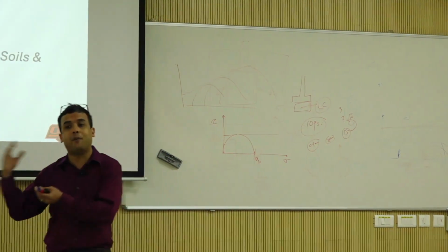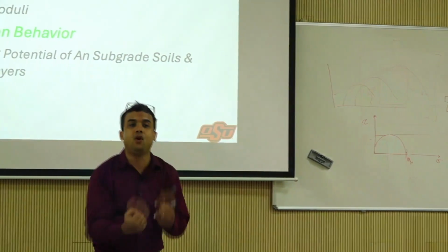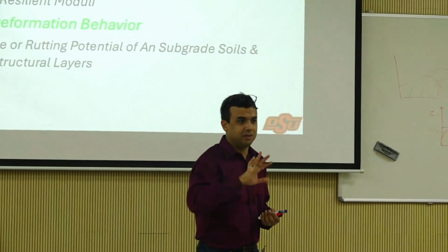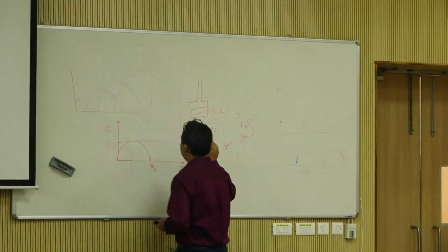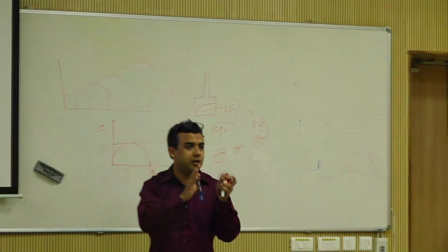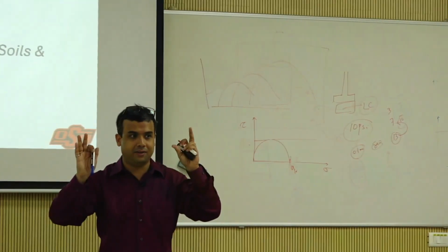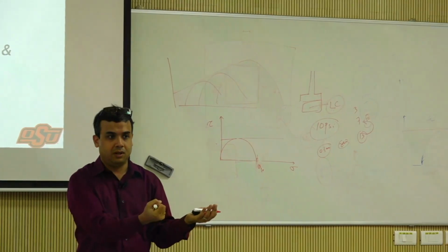Whereas when we go into modulus testing, you will see that I'm going to apply a 10 psi load pulse every 0.1 seconds and stuff. Because it's all triaxial, I wanted to give you this background on what is stress control versus what is strain control. So just remember that. What are you asking the system to do?